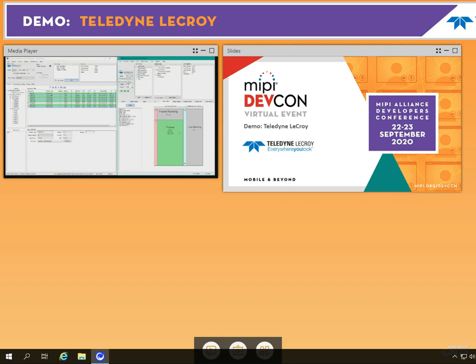Along with video analysis, the Envision X84 allows for more detailed timing analysis. In the Timing Analysis tab, we can select all our events and then measure frame start to frame end, or better yet, frame end to frame start. This will show how much time was occurring between frames. We can also look at line end to line start to show us the amount of time spent during line blanking. Once you've selected your parameters, select Analyze Event Timing. Here you'll see your average time, your minimum time, and your maximum time based on the number of occurrences of the parameters you were looking for.